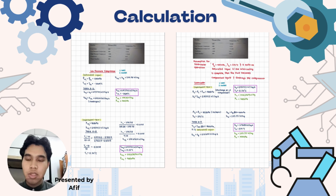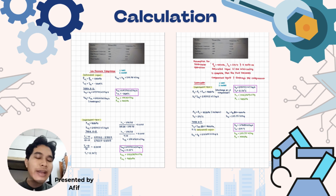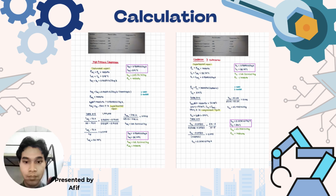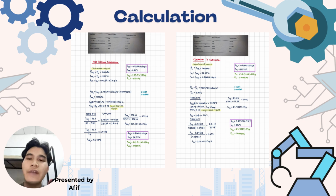For the outlet, it's going to be superheated vapor. This is where it changes, and the values are also as stated below. And for the intercooler, the phase at the inlet is superheated vapor, and then it's saturated vapor at the outlet. Now, moving on to the high pressure compressor, which is after the intercooling part.